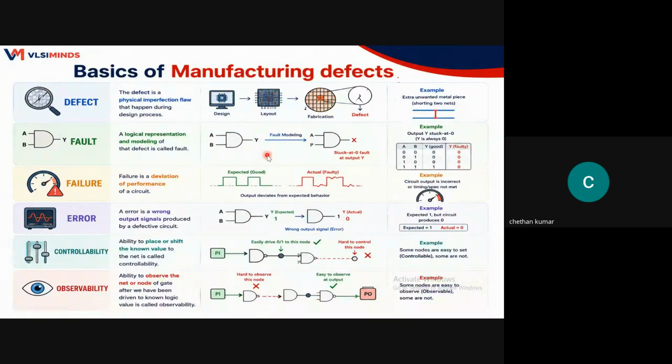Okay. So that means that here, let us assume there is an AND gate. So the AND gate output is stuck to 0. Let us assume this is connected to the ground. Irrespective of your inputs A, B, always the output will be 0 only. Correct? This will be faulty. Actually, if it is 1, 1, then I should get 1. In all other cases, 0.